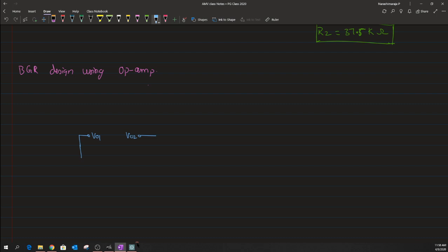And we know that this guy has to be realized with a diode connected structure. So in this case, I am reverting back from PNP transistor to an NPN structure, and one could still use the same, PNP or NPN, doesn't matter, or one can even replace this diode connected structure with a diode which is forward biased. Okay. So here we have Q2, and this is n times larger than the emitter area A of Q1, and this is what we have at the bottom.